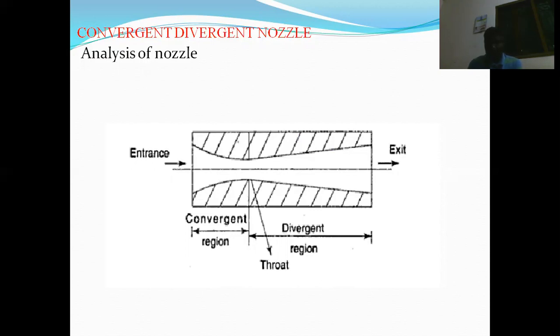While it is passing through the nozzle, some amount of the heat and the pressure of the steam will be converted into kinetic energy, and the steam will expand in an isentropic manner.